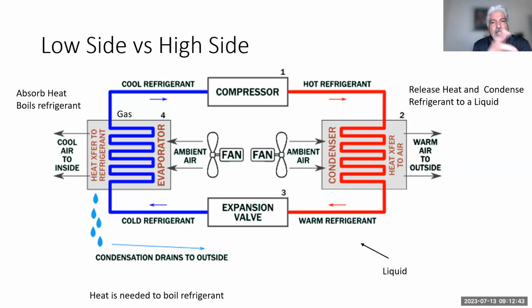But what moves the refrigerant, like we said in part one, is the compressor. The compressor not only generates the pressure that we see on the high side, but it also creates a suction, which creates a low pressure on the suction side. So the compressor has a big job. Not only is it moving the refrigerant, the refrigerant is moving the oil, but it creates the high pressure and the low pressure. However, it cannot create a high pressure unless it pushes up against something. It's got to have a restriction, something that it pushes up against. That would be the orifice tube or the expansion valve.